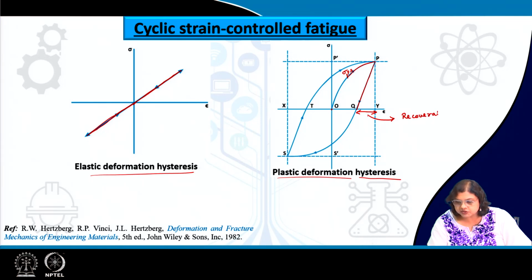Now, recoverable strain is nothing but the elastic strain of a material, right. So, that part Q to Y, that is the recoverable strain. On the other hand, O to Q, this is the non recoverable strain, or this we can term as the plastic strain.